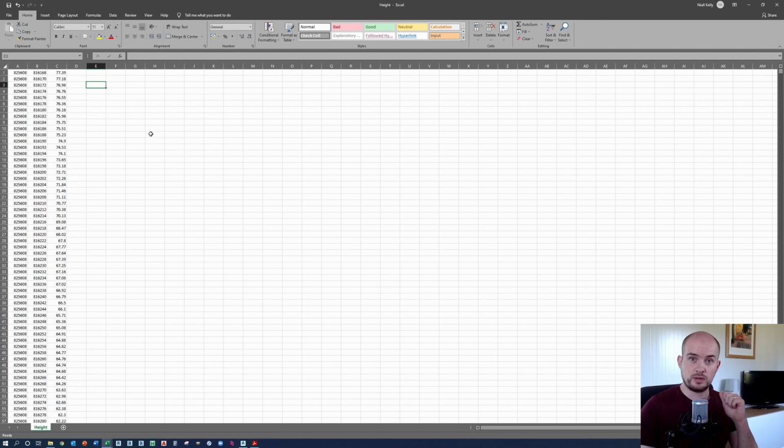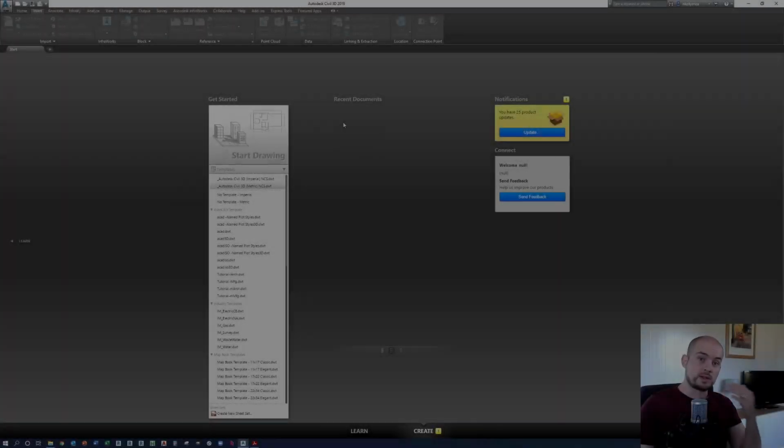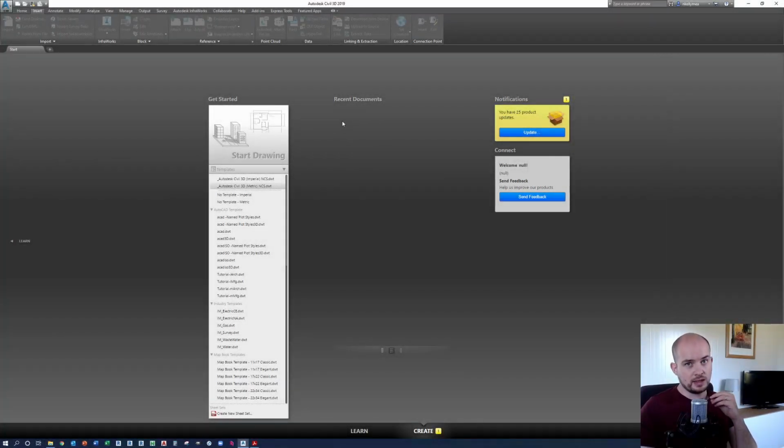So that was step one, which is knowing how to format your Excel documentation prior to bringing it into Civil 3D. So step two, I want to talk about how to create the initial surface within Civil 3D. So this is basically the instigating steps to bring in a surface, or a thin surface in this instance, into Civil 3D that then the point data will inform, if that makes sense. So what you do is you assign a surface to the model environment first, and then you bring in the point data, which will control the various contours and points on it, okay?